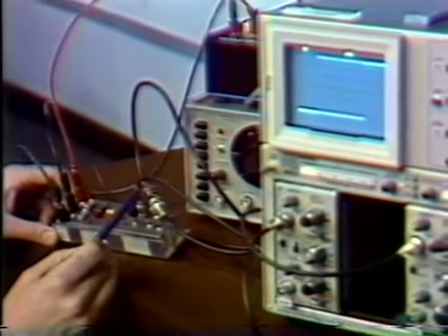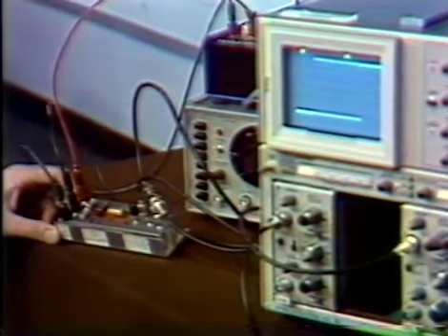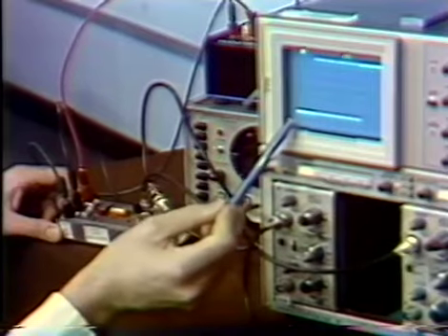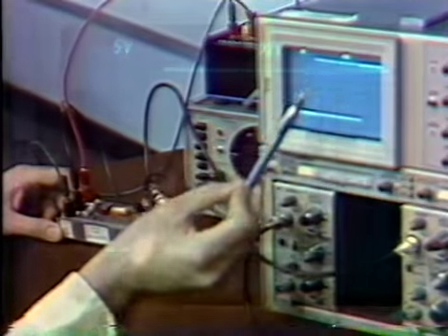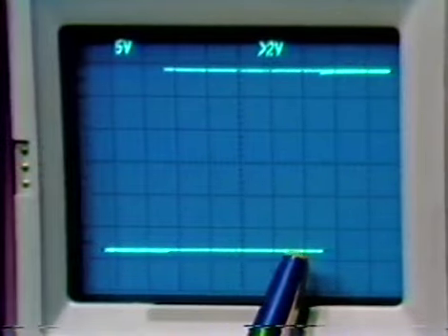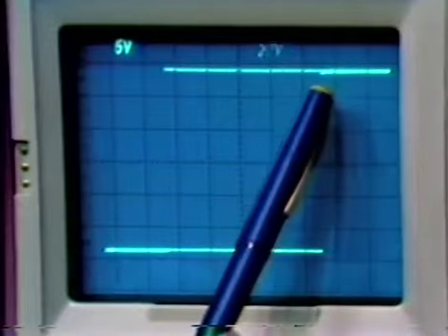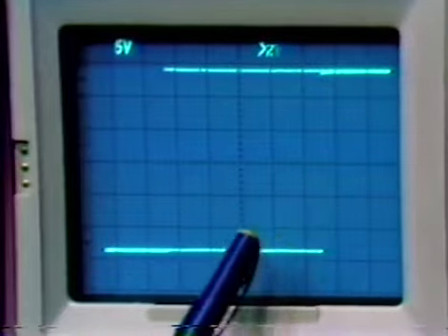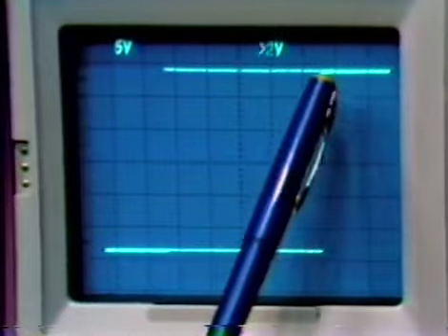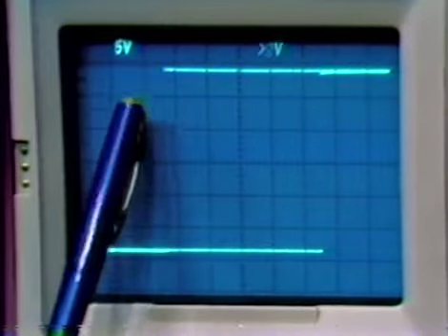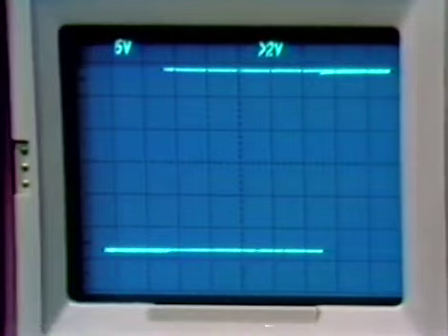We also then look at the output of the Schmitt trigger on the vertical axis of the oscilloscope, and we see on the oscilloscope screen the Schmitt trigger characteristics. Presumably there's a very rapid transition here in a positive direction, a very rapid negative transition here. We don't actually see those, but we do see the flat portion of the characteristics. Here's the input signal going positive, then reversing, going negative. The Schmitt trigger flips. So we're tracing out the characteristics that we expect from the Schmitt trigger.